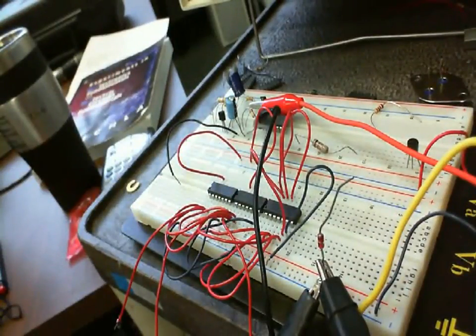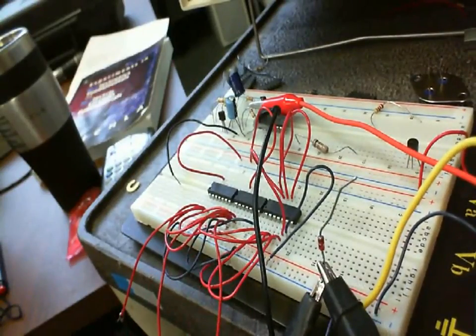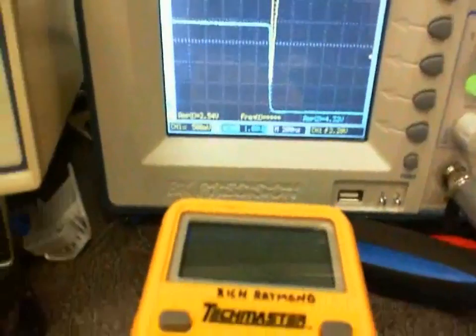And what I'm doing is I'm applying a digital pulse coming in. And then my other input, I'm sending it through a series of inverters. I think I got 3. It's got to always be an odd number because it's got to give you that inversion. And what we're doing is we're taking the propagation delay and we're ending up with this.